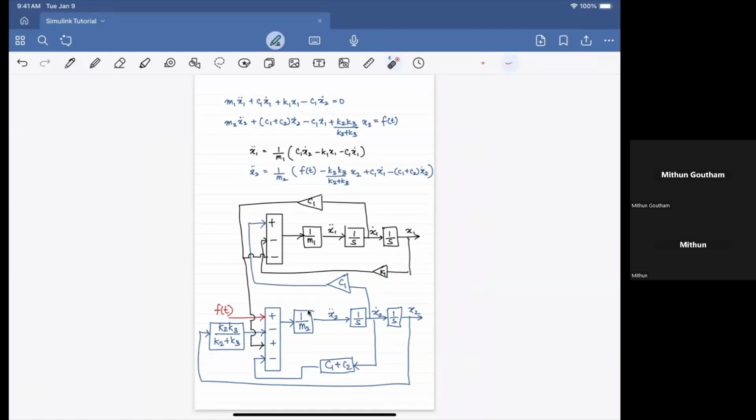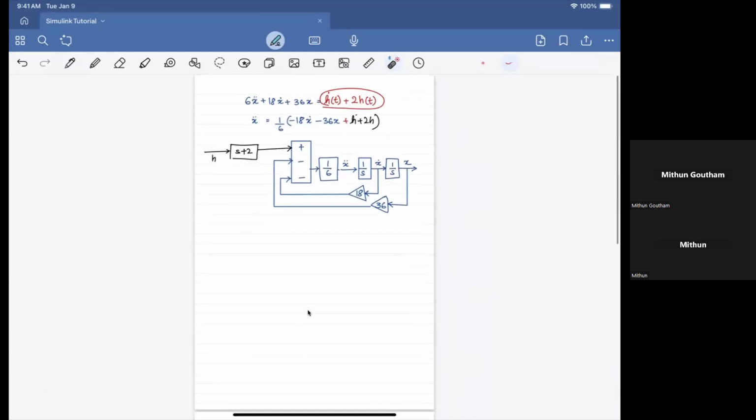In reality, you might want to be changing those parameters. And sometimes you will have C1 appearing in multiple places. And then you're setting yourself up for failure if you go and put in those numbers everywhere inside the Simulink model. So what we did here is basically not good practice.